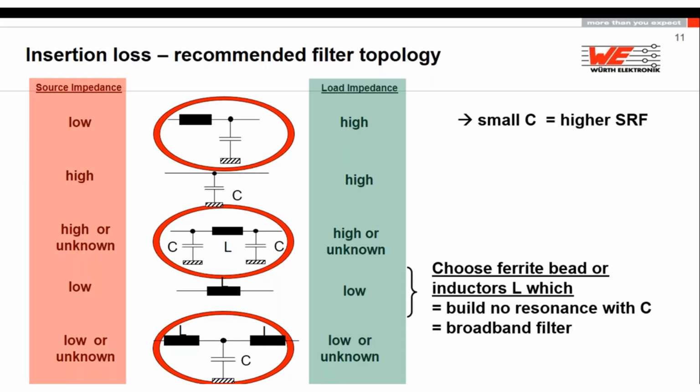The problem is that the Q factor is not included in the formula, and most people will forget or will deny to think about what the Q factor is. Please be aware of this Q factor, which is crucial for your filter, because the Q factor for an inductance in a filter must be very low. If the Q factor is too high, it may ring your filter. Your filter starts to increase the amplitude or multiply the noise peaks and will not be a filter.